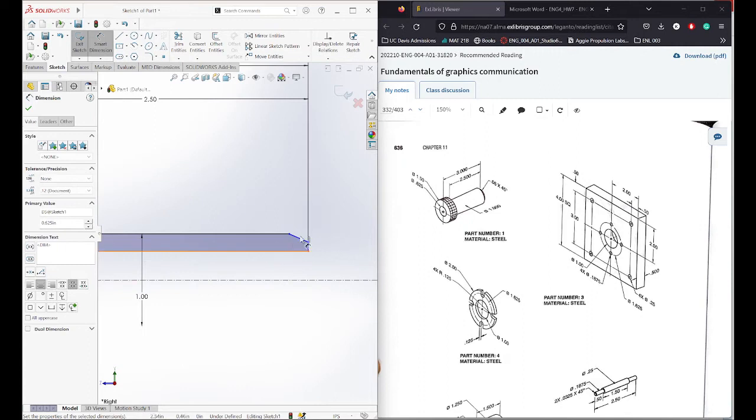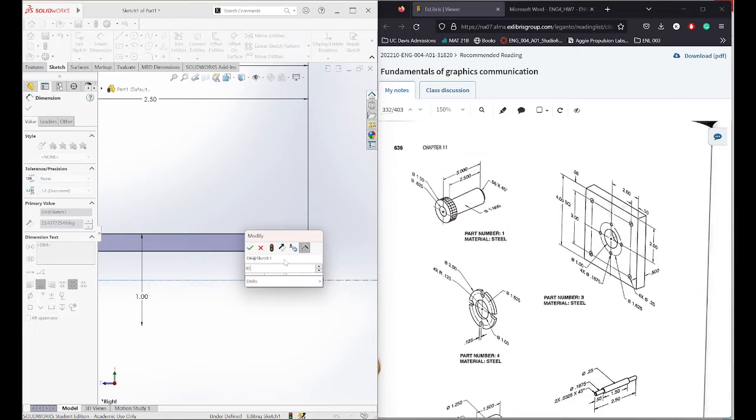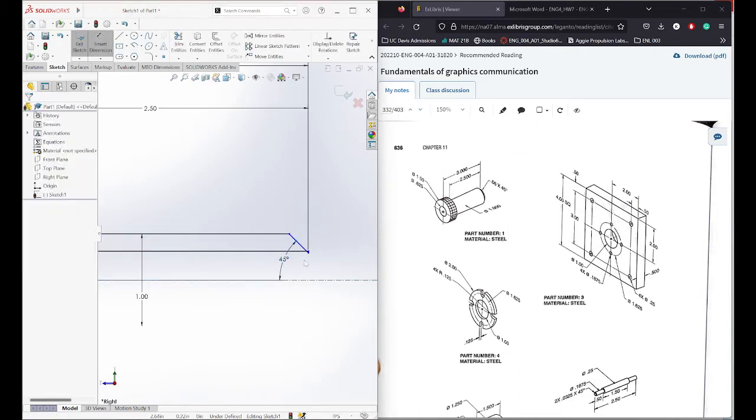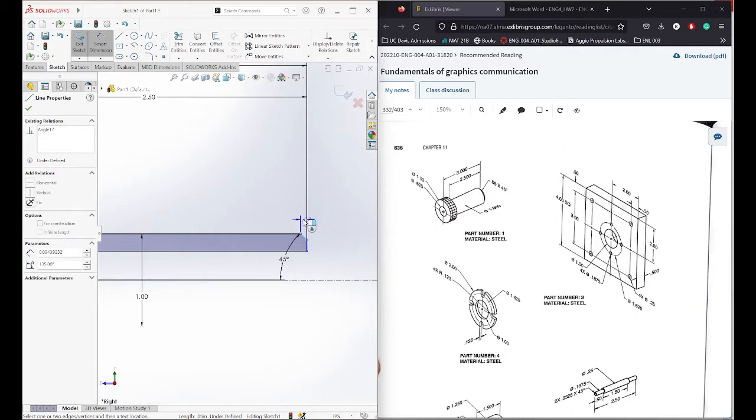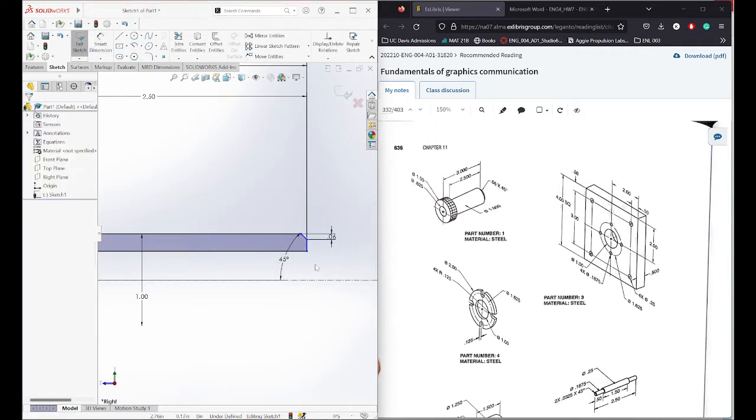And then for the chamfer, what it will tell you is the width and height, which is 0.06, times the angle of the chamfer. The angle of the chamfer, which is always to a horizontal line, or like an angle to the axis of the line, is 45 degrees. So this thing is 45 degrees. And then I'll just move my sketch around to make it easier to see. And then the height or width, you can select either one, is 0.06. And then what else do we need?